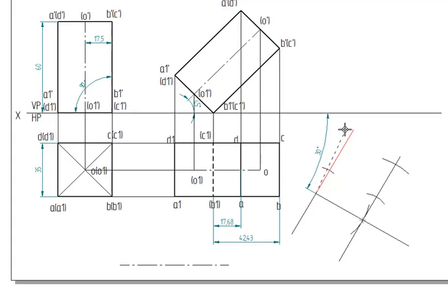Now, keeping this distance, B1 to A1 is how much? 24.75. I got it. I'll go again arc by center point. So from here I'll cut a radius. Now I'm going to draw a line.